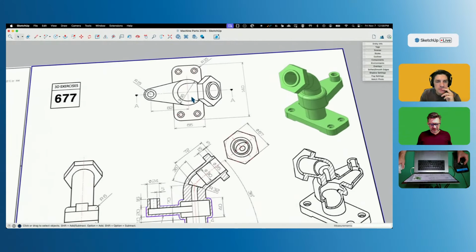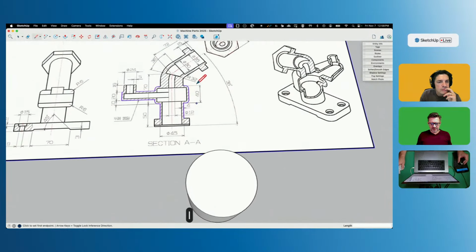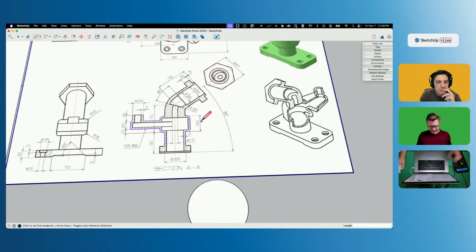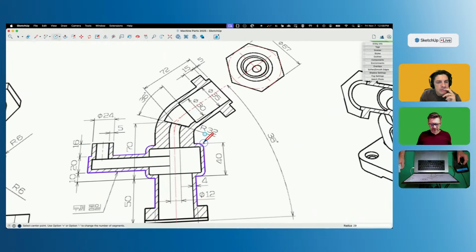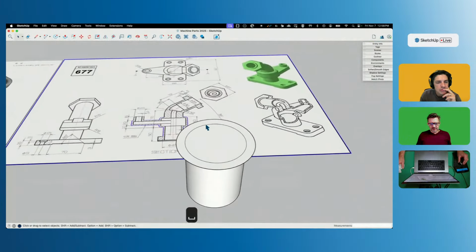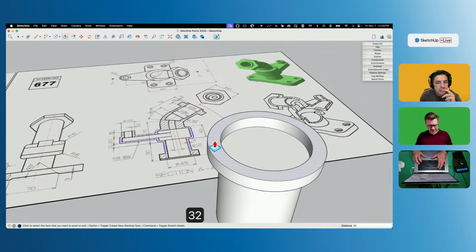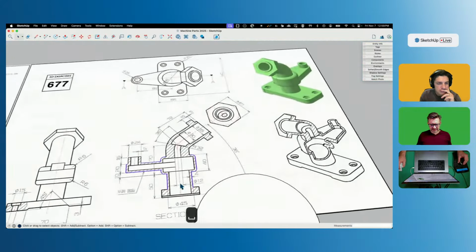All right, so I need to know, oh, right here. That's 66? 66, okay. So half of 66 is 33 minus 4 is 29. So if I put another circle from the middle here, a radius of 29, and then that is 40 minus 4 and 4 for the wall width, so 40 minus 8. All right, so that's these two pieces.